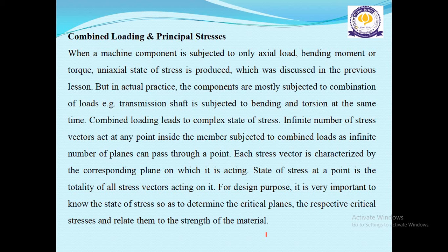Combined loading leads to a complex state of stress. An infinite number of stress vectors act at any point inside the member subjected to combined loads, as an infinite number of planes can pass through a point. Each stress vector is characterized by the corresponding plane on which it is acting. The state of stress at a point is the totality of all stress vectors acting on it. For design purposes, it is very important to know the state of stress so as to determine the critical planes, the respective critical stresses, and relate them to the strength of the material.